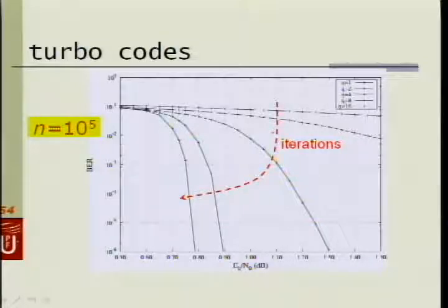How can we understand the convergence property of turbo codes? It's very difficult. Rüdiger Urbanke will tell you about this early next week. But anyway, the exact analysis is very difficult, though not impossible. On the other hand, there is a technique that I'm going to describe in a minute called the EXIT chart technique, that from an engineering point of view works very well because it's an approximation, but it yields a lot of information about the convergence property.